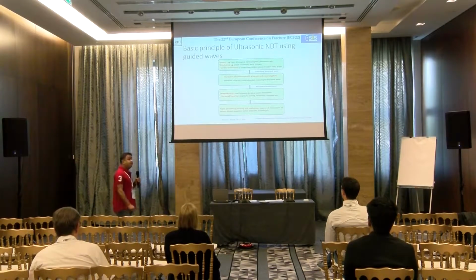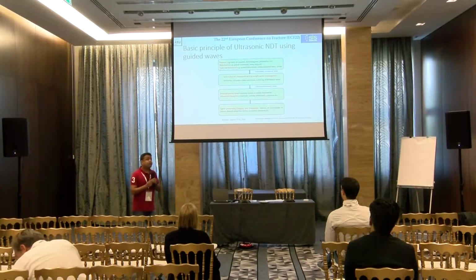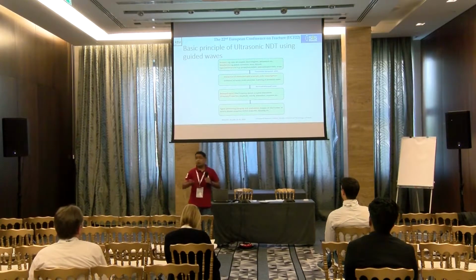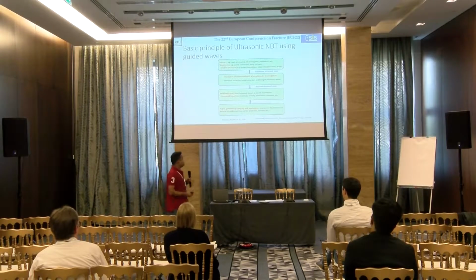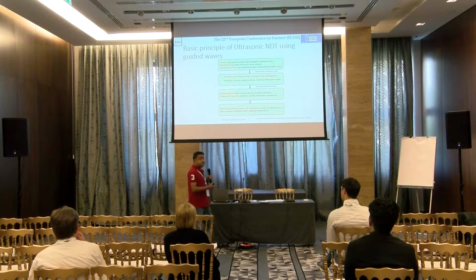When the transmitted ultrasound wave interacts with the composite structure or sample, the ultrasound can be reflected and refracted. In-plane ultrasound waves can be converted into out-of-plane or vice versa. So it creates some more complexity. That is why, to extract, measure, and estimate the parameters of ultrasound waves such as amplitude, velocity, resonance, and attenuation, we need efficient signal processing techniques or imaging techniques. In this way, we can extract the size, location, or characteristics of the defective signals.